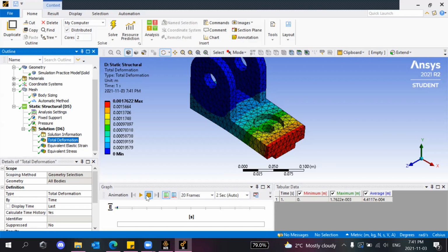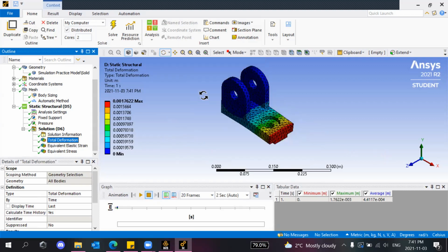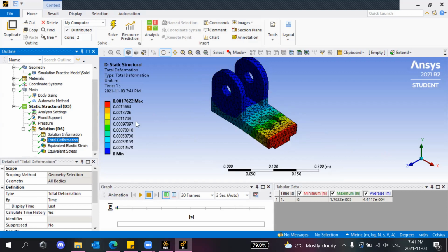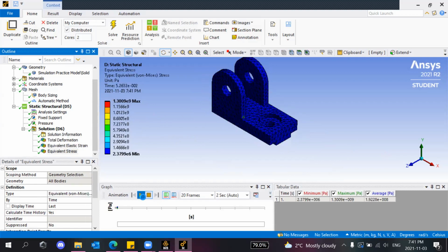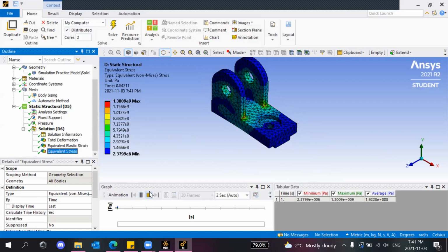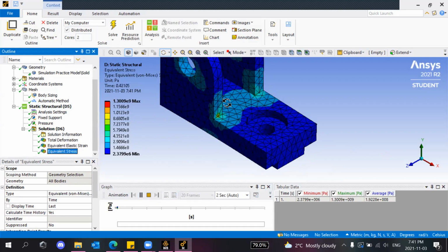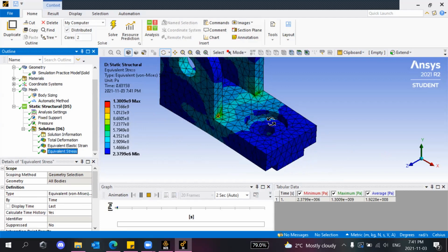So some important questions to ask when you have a result like this is, does it make sense? And there are a couple ways you can go about it. The first thing is, do the stresses that you're getting make sense? Are you getting abnormally large stresses over here? Or are you getting a stress such that your material is failing, right? 10 megapascals shouldn't be breaking the material so much, right?